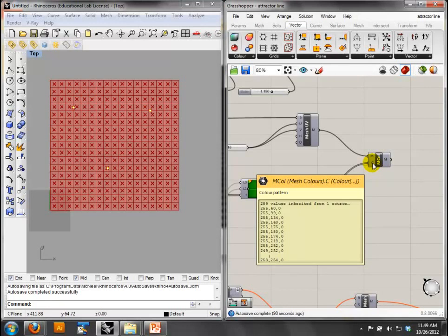You can't just throw color on an object. This is where it gets tricky, and I'm going to try to explain it. You actually have to convert the surface to a mesh. Surfaces are really smooth, basically made up of NURBS, which are these smooth curves. A mesh is a bunch of little square or triangular facets, and that's actually what computers basically work with. That's what your video games are. Even the NURBS actually get turned into meshes before they get drawn on the screen.